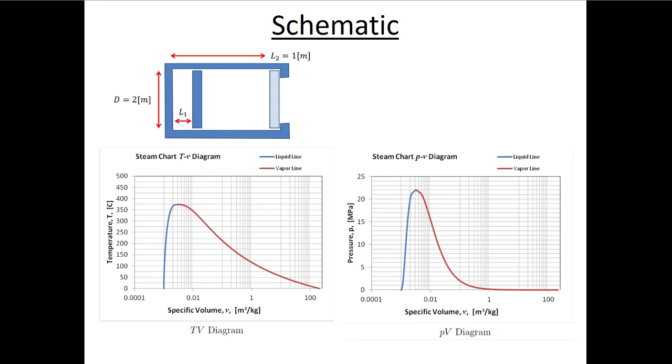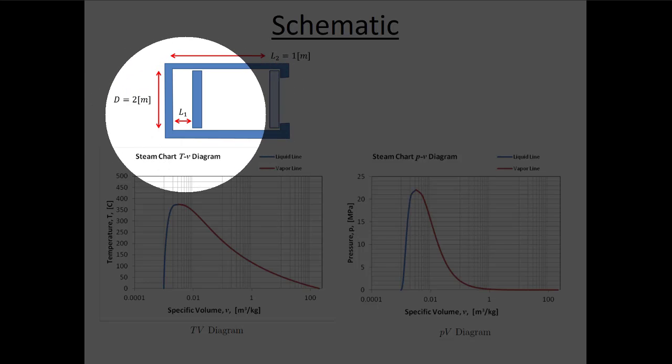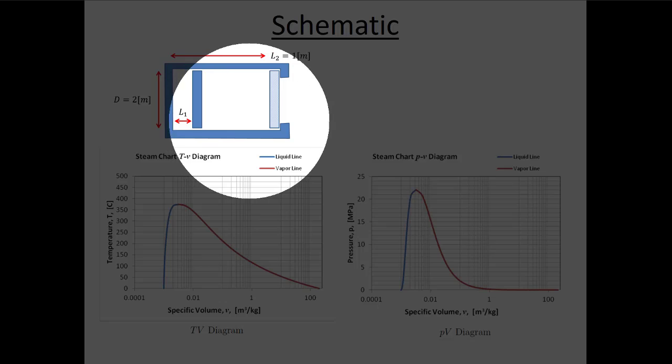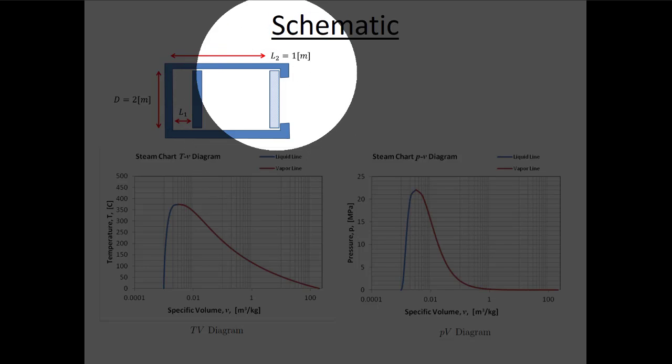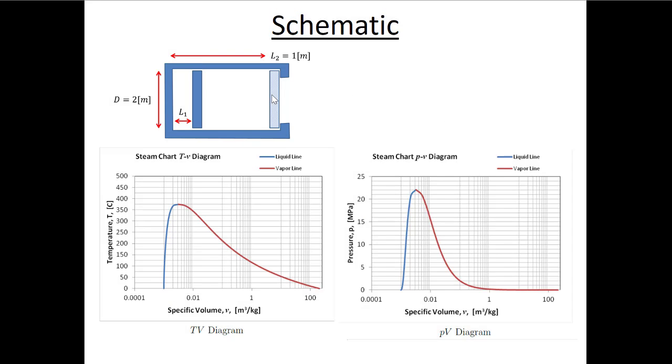So the next part of our solution process is to draw the schematic, right? The schematic is given in the problem where we have this piston-cylinder assembly, and we start at some distance, we're adding heat, so this water eventually begins to change phase and then expand, and we end at this L2, and the piston stays in the same position for that whole process from state 2 to state 3.